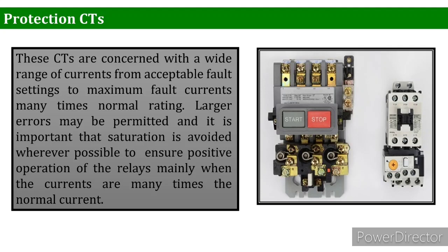You can see if any protective instrument shut down all the plants, that is not feasible, as we studied in our first lectures that selectivity is the important trait of any protection equipment.